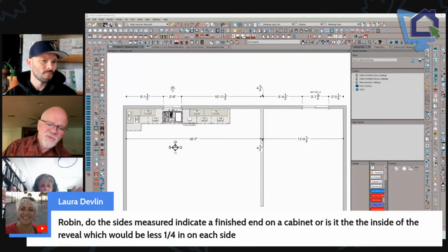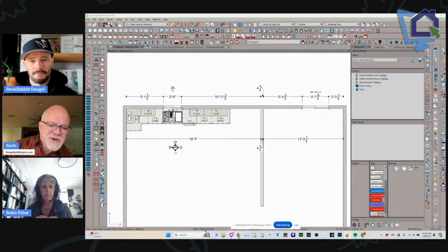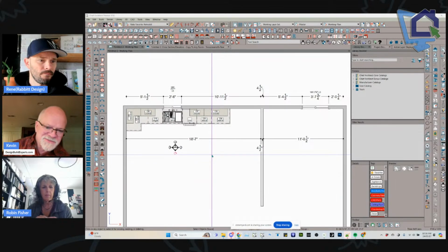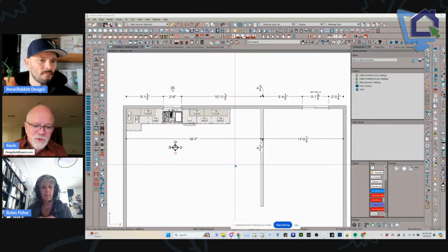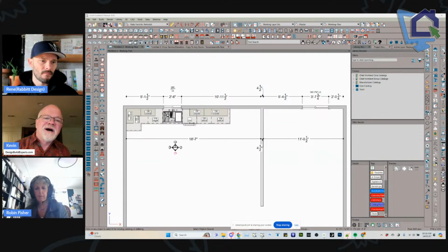Well, you're looking at it from the cabinet itself. If you look at it from the other way, if you are dimensioning to the corner space from the kitchen, maybe you're looking at the hip knocker as you round an island and you're looking at what the clearance is between that and the next obstacle, then measuring to the corner is the right place to measure. So, at a diagonal, for instance. So there are places where the corner makes sense, or they wouldn't have put it in the tool. But for your typical use, laying it out to the nearest wall or to the nearest cabinet or whatever, then the corner doesn't have any purpose.